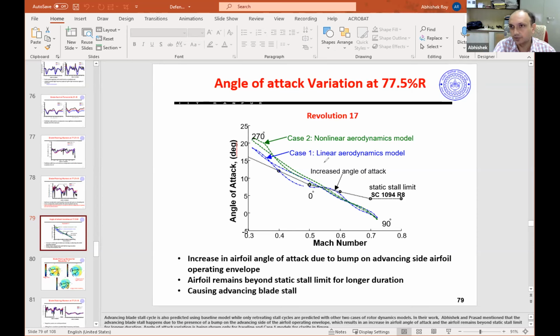At the leading edge, a separation bubble is formed. This bubble will then travel along the chord of the blade. While it keeps traveling, you actually get a dramatic benefit: your lift keeps increasing because this is a suction bubble. If you plot the CP on the top, it will create a higher peak in suction, so your lift keeps building while it is traveling. I will give you an example by drawing something here.